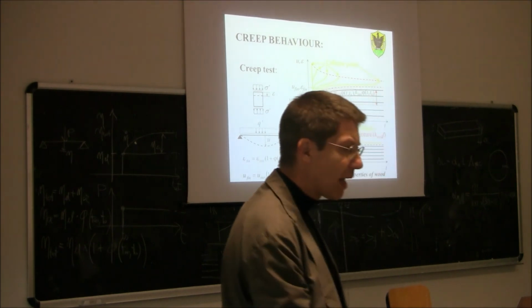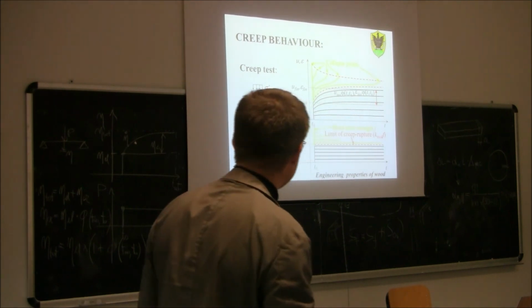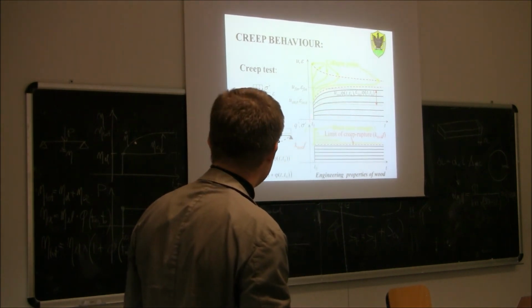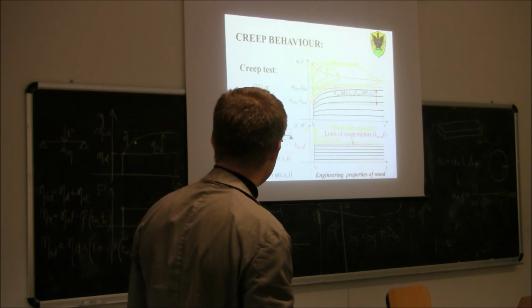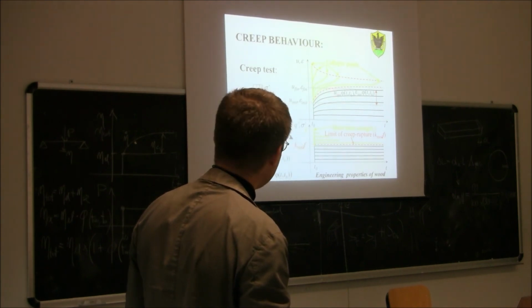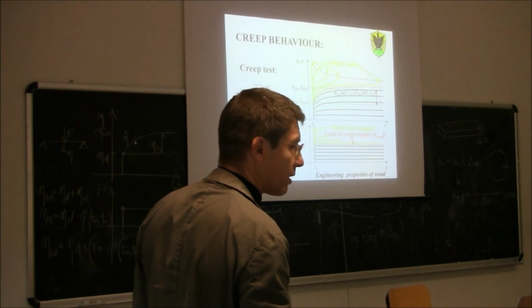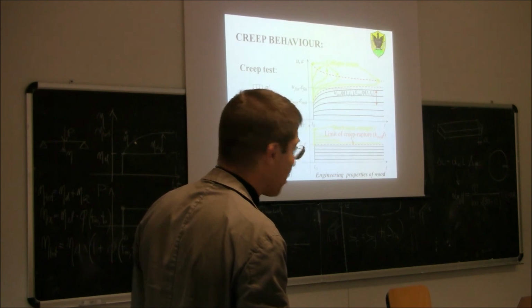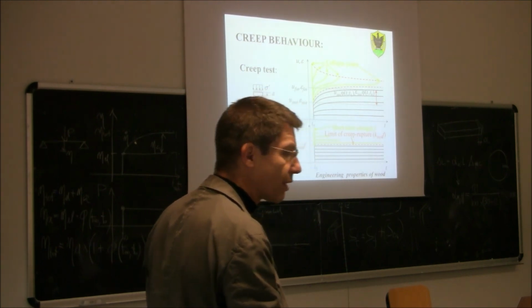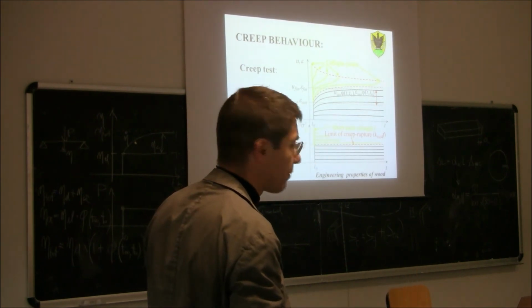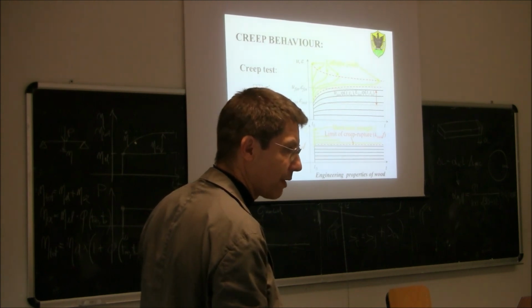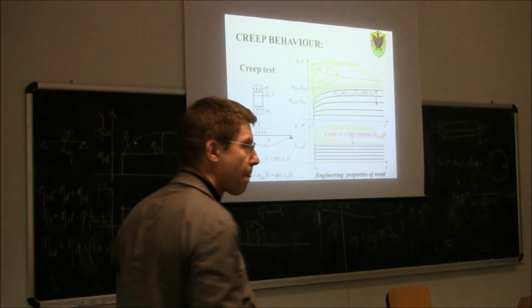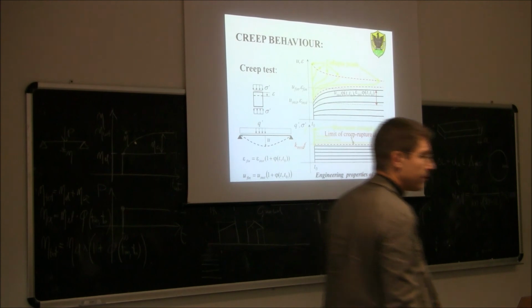No, above this line you will have creep at the very beginning. Look at this curve here. This is called primary creep. You see that there is some increase in deflection. Then you have a secondary creep, where the curve is almost linear. And then we have what is called tertiary creep, so the rate of deformation increases again until you get to failure. Okay? Other questions?